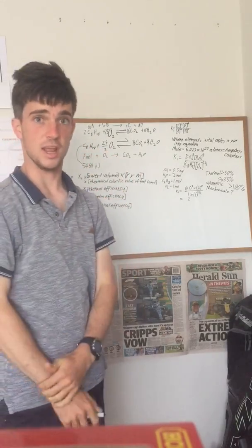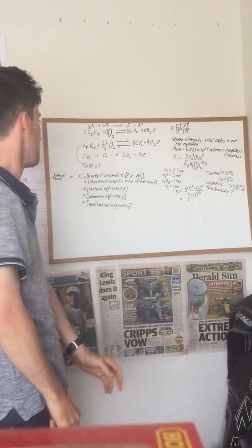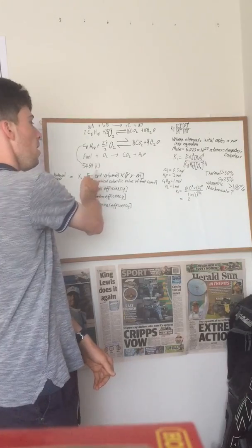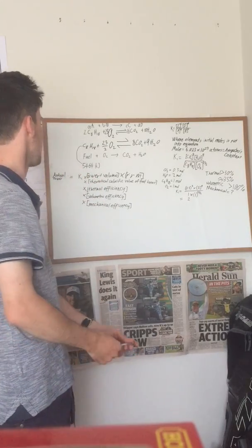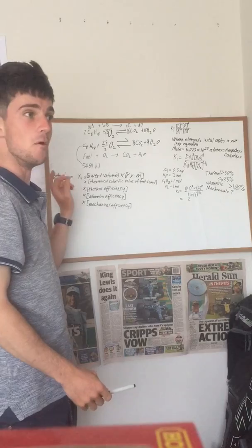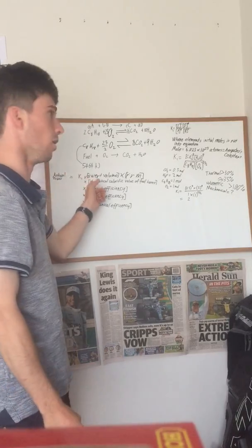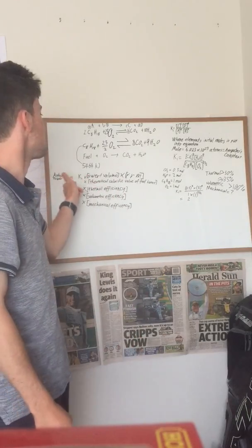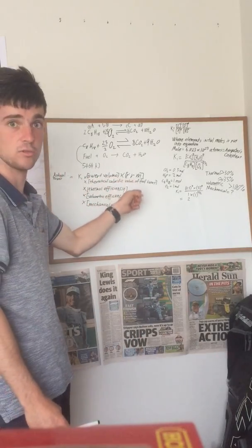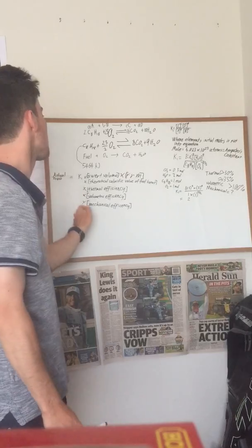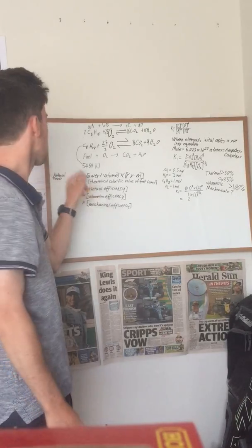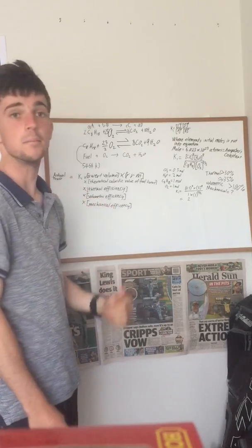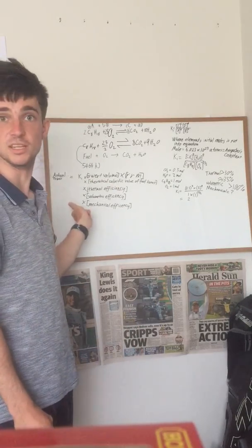So the equation now becomes actual power equals K1 multiplied by swept volume multiplied by RPM multiplied by the theoretical calorific value of fuel burnt multiplied by thermal efficiency multiplied by volumetric efficiency multiplied by mechanical efficiency.